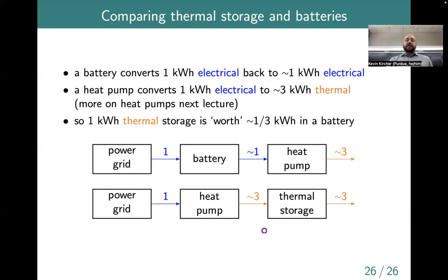Another consideration here that's sort of interesting. I guess it's not really illustrated here, but there can be advantages in being able to downsize the heat pump. If you are able to run both the heat pump and discharge the thermal storage at the same time, suppose on a really cold night you have heated up a bunch of hot water, and you can run the heat pump at capacity, and maybe it's too small to by itself keep the building warm.